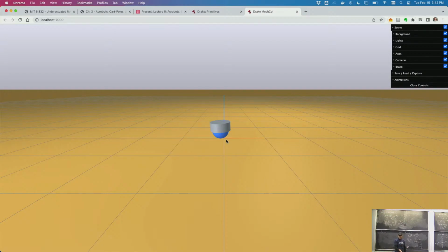This is what people do when you're making cars or unicycles or bicycle models or whatever: you typically write the coordinates in the constrained dynamics. And so in the dynamics of that constraint, you have fewer state variables, and then your linearization is good. Okay, you can take gradients through full dynamics with equality constraints, but it's more work. To make this recipe work, I only write the variables such that the robot is always on the plane, can't lift off the ground.